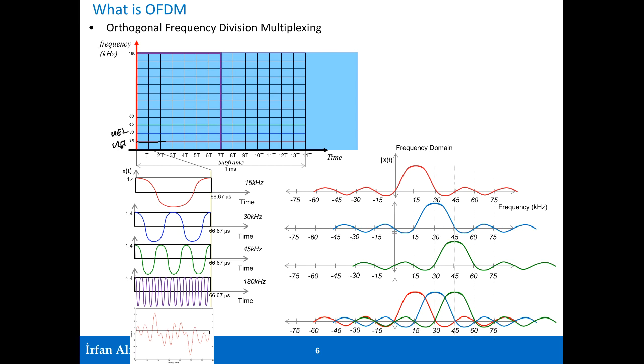So you can be sending the bits of information in each frame to UE1, and then in another sub-frequency band to UE1, and then to UE2 you could be sending it over here, and over there. You could do this really arbitrarily on a very fine subcarrier basis, but coordinating this with the mobile is much more complicated.